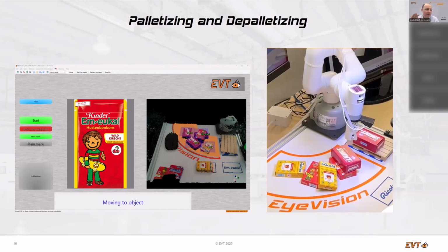Of course, if you have a suction gripper like here, in most cases, you simply can press it and hope that it holds. But if you use the full 3D command set, you can tilt because you know the angle, you can tilt the suction gripper so that you are at 90 degrees when you grab the part.